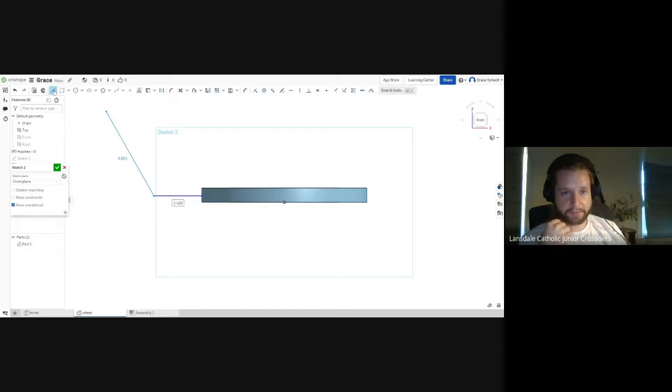And you can make that whatever length you want. And then that's going to be the center line of your spoke. So you're going to rotate something around here. You're going to create a revolve feature, okay? So leave that as it is, or you could dimension it, sure, that's perfect. If you would like, put a length on it. Perfect. And now do you see how that thing became off of the edge? Yeah. You're going to want to constrain that so that it is on the edge.